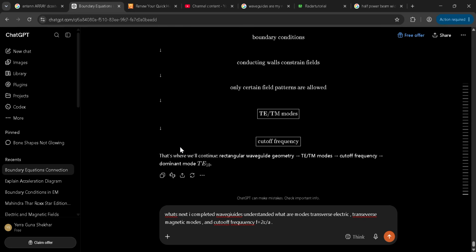First we calculate, what we do. Yeah, yeah. For a circuit we have A and B, two open terminals. We use some KVL across there, and then we first calculate the equivalent resistance by ignoring the open resistor components.